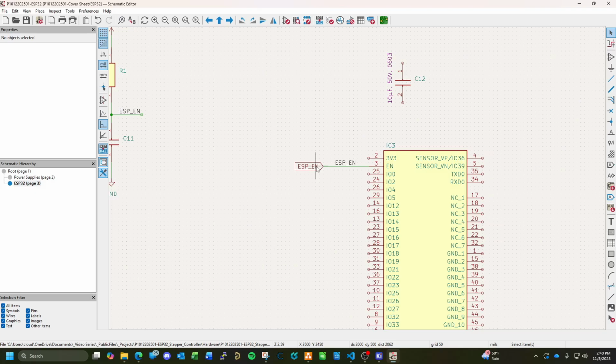So when you transfer over to your PCB, they'll all be connected. The reason I'm doing this as a port is this sheet's not big enough. I think I'm just using a letter layout, which is perfectly fine. Maybe down the road we'll create an 11 by 17 template sheet, but for now we're just using the default they gave us. So I'll have to put the UART bridge chip on another sheet, which isn't a big deal.